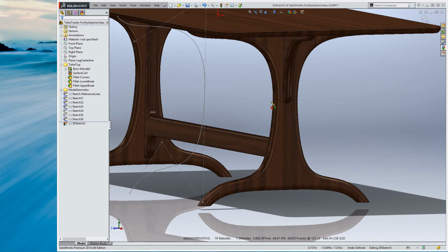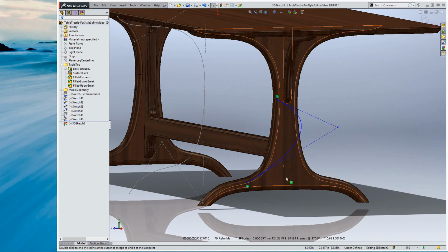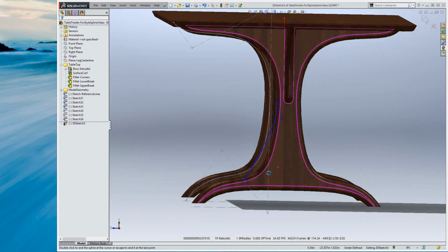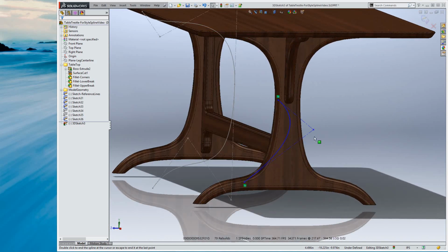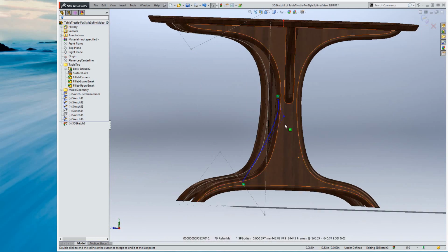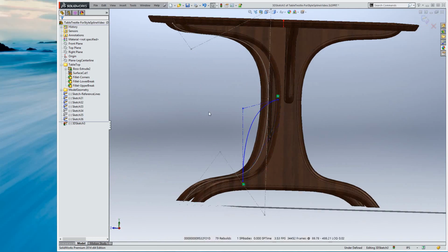Pick a point, then we'll pick one out in space. Then I'll bring it back. The benefit here is 3D splines are quite difficult to work with, but style splines, because there's less direction control and more just controlling these vertices in space, we can add dimensions to this point in 3D space, and that makes a lot more sense to me.